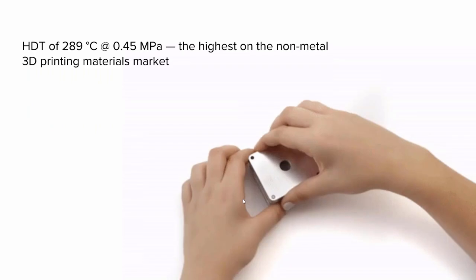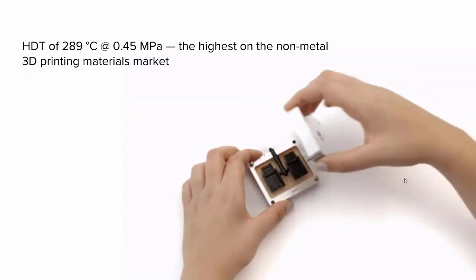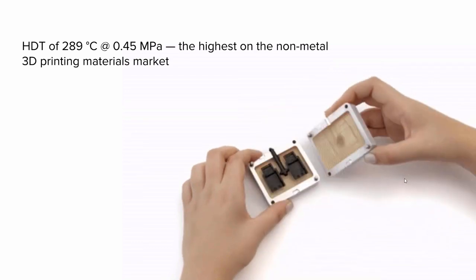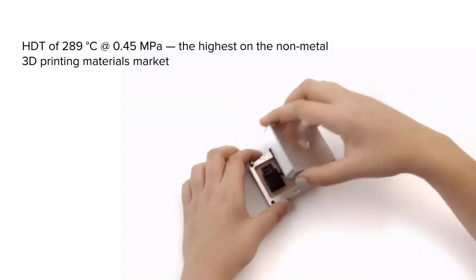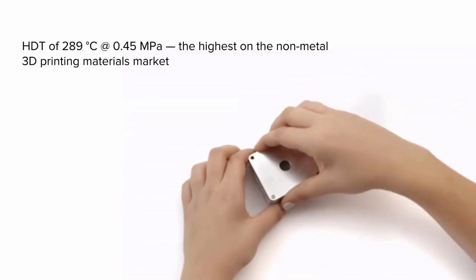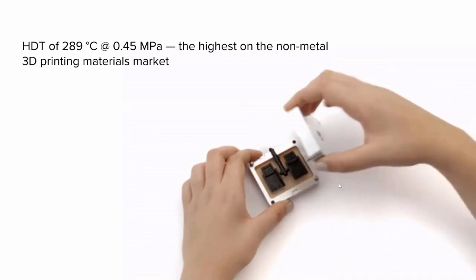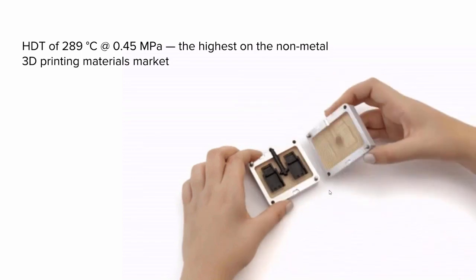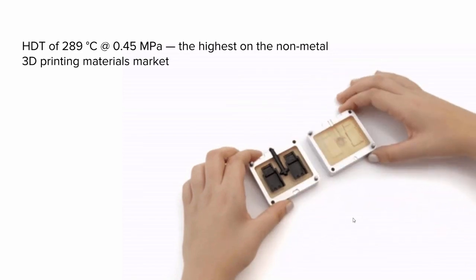High temperature resin. This is a material with a heat deflection temperature of 289 degrees Celsius at about 60 psi. This is the highest heat deflection temperature in the non-metal 3D printing market, so in the plastic 3D printing market. And this material is really designed for printing overmold tools or prototype injection mold tools. Also, I've seen it used for mounting components and brackets on the assembly lines that are in really hot environments.